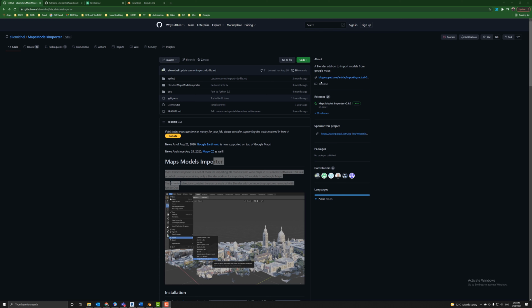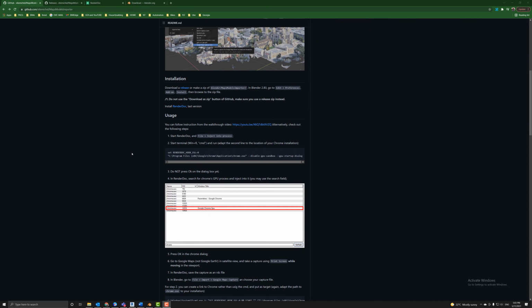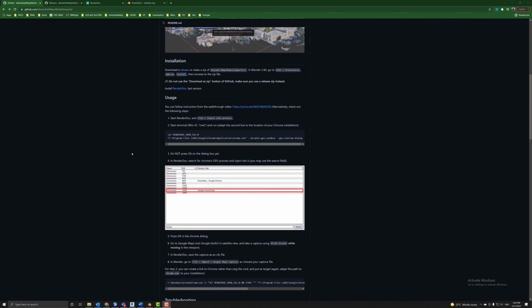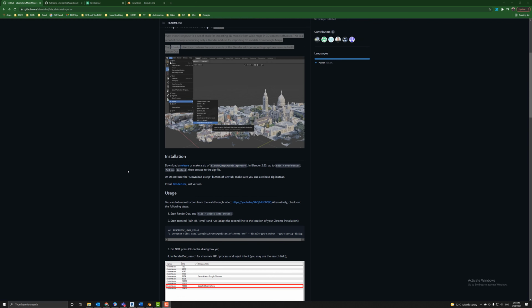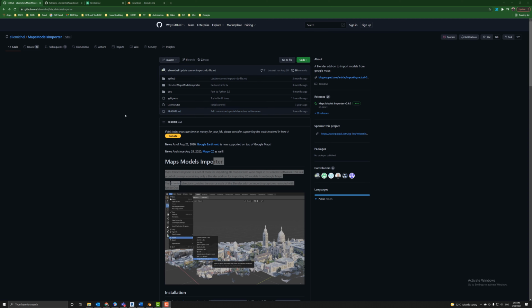Okay, so we're going to move on to discussing how to actually go about doing this. All of this is really possible because this user, Ellie Michael, has provided a maps model importer for Blender. This really allows you to use this other program, Renderdoc, to get your Google Maps 3D geometry into Blender so you can then export it out in an appropriate format to make an Enscape asset. There's some really good information on here. I've got links in the details underneath this video to where to go to get this, but step one is going to be to download this maps model importer.